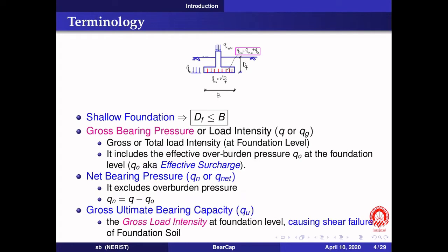Now there is some usually applied terminology. Suppose I have a footing here, and we call it a shallow foundation. A shallow foundation is defined as the one whose depth of foundation, shown here as Df, is less than or at the most equal to the width of the foundation, which is denoted by B here.